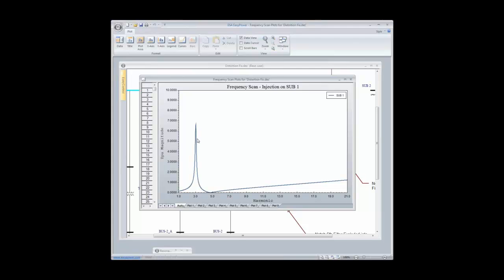Basically, every time you have a combination of inductance and capacitance in any form, whether it's just because of a capacitor bank on the bus or because you have a filter on the bus, it's like one of those balloons that the clown ties up. Okay, so you're holding that tubular balloon. If you pinch it, it's going to make the rest of the balloon expand. That's exactly what we're doing with a harmonic filter.